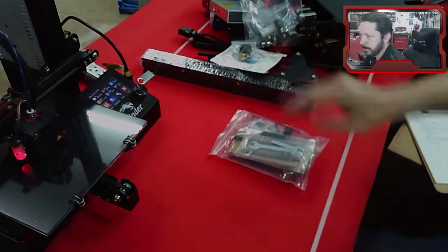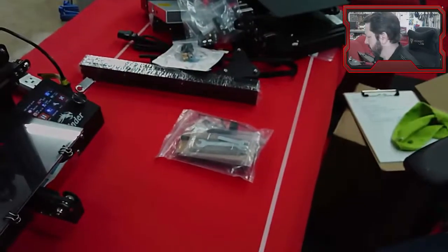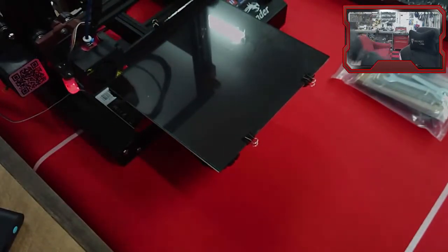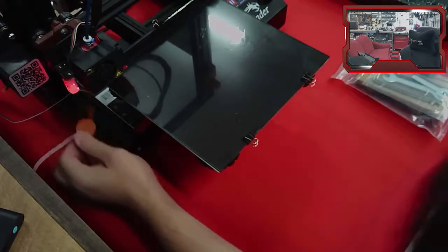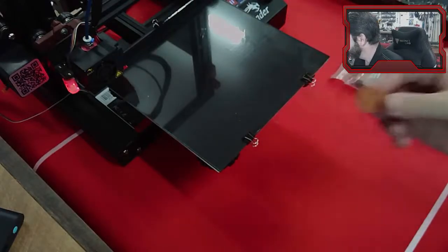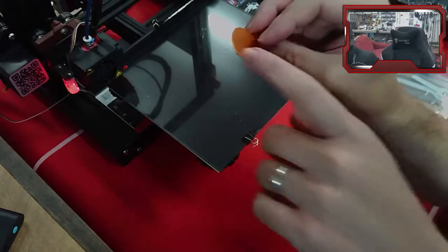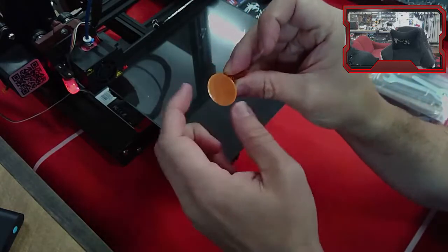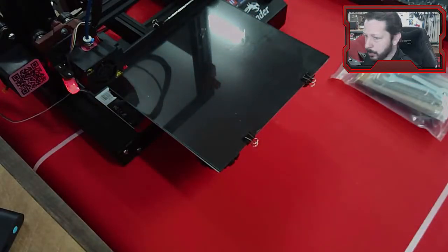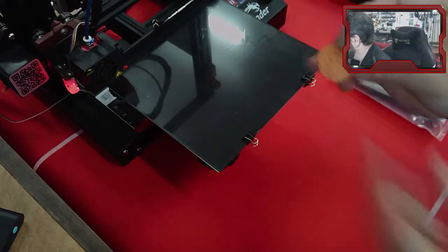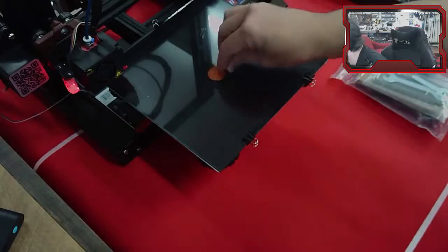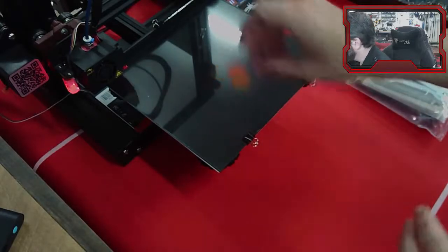So this is our printer. And this guy finished up just now. Oh, but it didn't stick. All right, so this is something that happens sometimes. On these, I didn't really pay that much attention to it. And like I said, it was the first print of the day. So it stuck for a while, but this doesn't have a lot of area. I should have probably either made it squish a little more or maybe printed some more removable material around it to keep it stuck down. But this is what happened. It stuck down for a while and then it came loose, right?